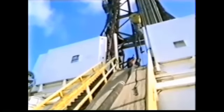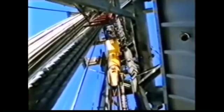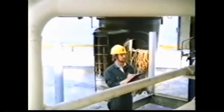Finally, the last test, the initial potential IP test, is conducted after the well has been completed and equipped in what is known as cased hole or closed hole, but before the well has been prepared for production. This very important test allows reservoir fluid volume or flow rates and pressure measurements to be accurately determined.